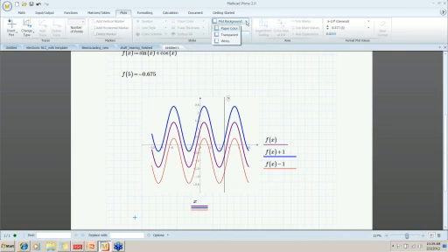There's something called plot background. We have the engineering paper here, which is very faint, but it's there, and it's set to the regular size mesh. When you have a plot, that engineering paper by default gets blocked out within your plot. So if you want to display it, you're going to set that setting here.